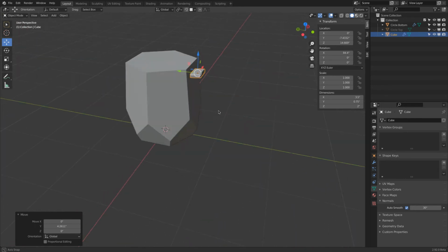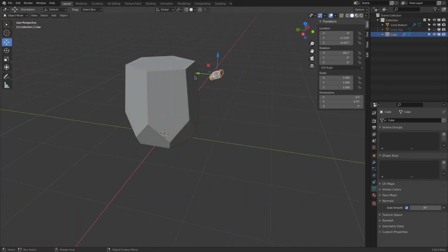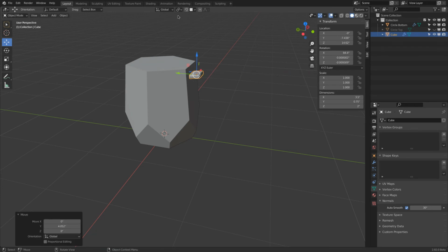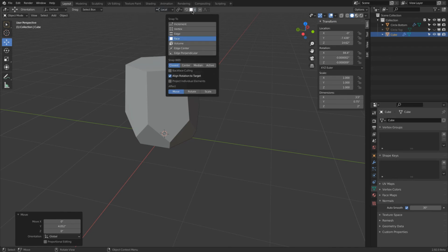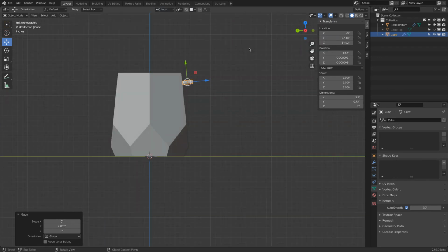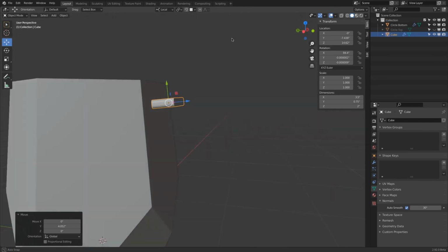Very good. So one more time. I can press along the green arrow, left mouse button, hold it clicked, drag, hold Control, release the left mouse button. Then I can turn local, turn this back off, go to wireframe mode.